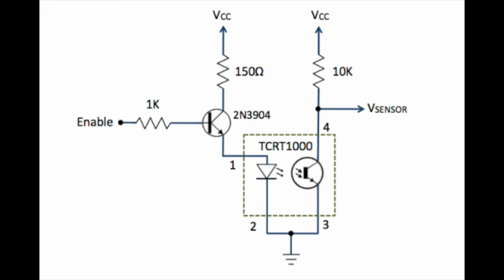Now in this exercise we will build a circuit that filters the infrared signal and employs the AC component peak to light an LED. At first we built this circuit using a reflective optical sensor, resistors and a bipolar junction transistor, as can be seen in this photo. We could see that the circuit was correct and working because we saw the infrared light from the optical sensor through a camera phone. It was interesting to see that the iPhone has an infrared light filter on the back camera but not on the front camera. So we could only see the infrared light through the front camera on our iPhones and Fabio's Samsung.